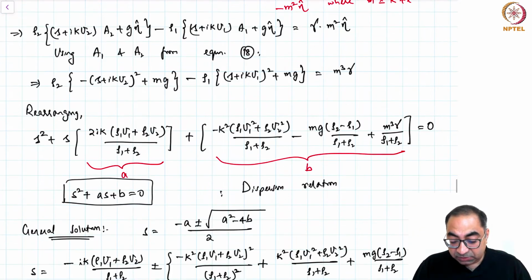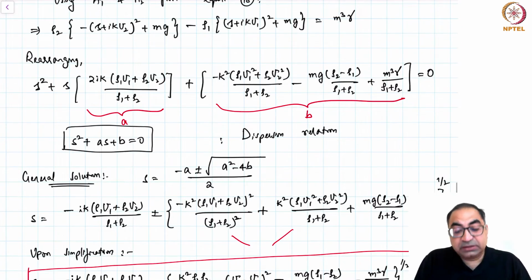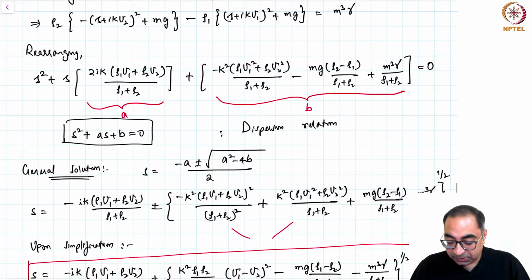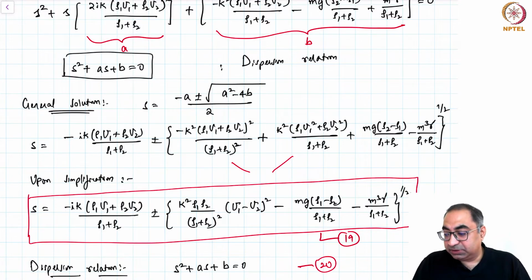So finally we were able to obtain a dispersion relation by taking advantage of the last equation, that is the normal stress balance. Note that eta hat, the perturbation amplitude of the interface, does not matter. In fact, for a linear problem, the amplitudes will drop out as expected, and therefore the dispersion relation that you can see on your screen is a simple quadratic equation, that's equation number 19.